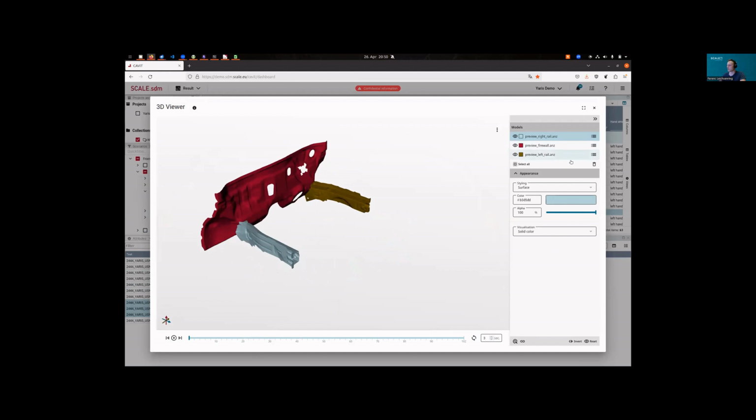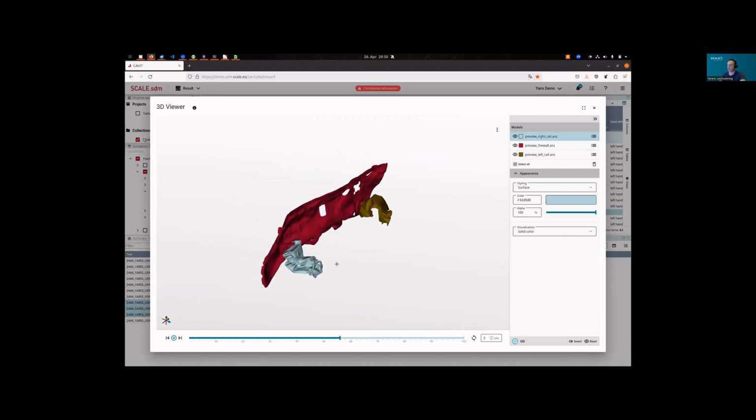And I think in the left rail and the right rail, we do have 2 layers exactly. So we integrated some basic tools like selection, deselection. You can fringe mechanical properties like stresses, strains, or plastic strains onto the parts as well. Here's just the color of the part ID. And then, of course, you can investigate how it's going to deform over the progress of your simulation.